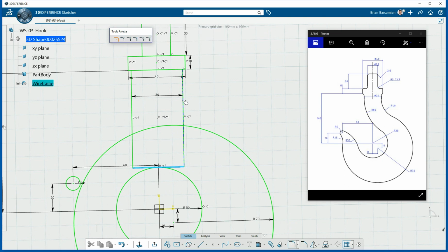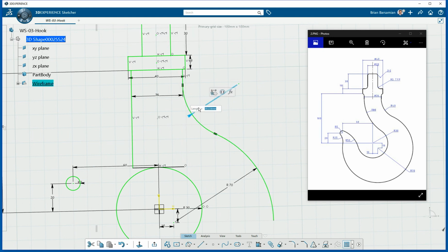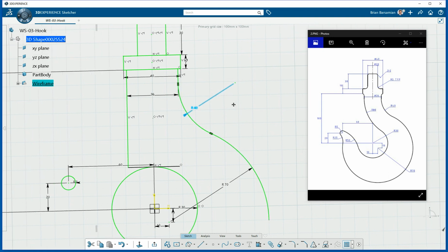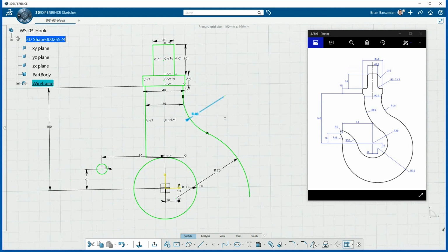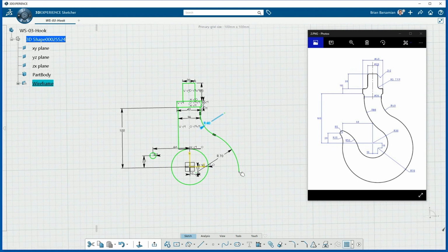And we will select this supporting geometry. Let's select this circle. Oops. Come on, let's try that again. We'll select the corner command. We'll select here. We'll select here. And then this is a value of 40. And look, it trimmed it and put our tangencies up and everything. That's just quite nice. And then we'll take this end and we'll just drag it around here. It's going to have to be somewhere around here for the rest of it.